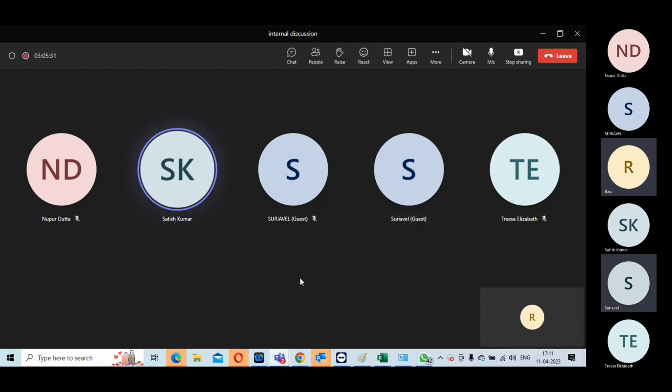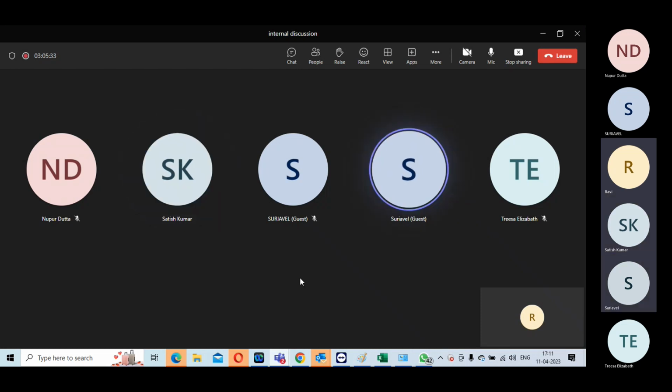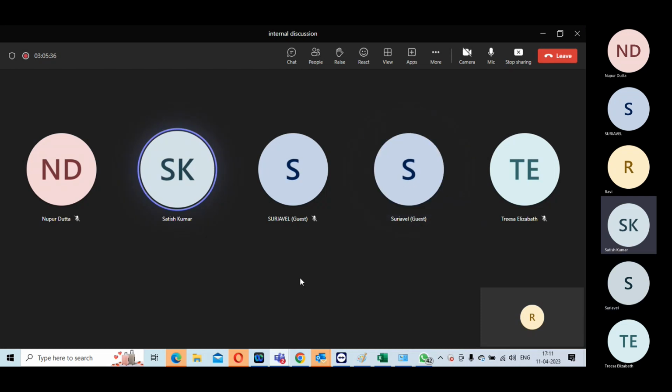Quickly, last 2-3 minutes. Sir, one more thing. Sir, what about building the clock tree, clock buffers and clock inverters, which is better? Clock inverters or clock buffers, which is better? See, the point is you should use both. Clock inverters have a lesser area and probably, because they can switch faster, I would prefer clock inverters. But while doing all ECOs, don't use any inverters, use only buffers.